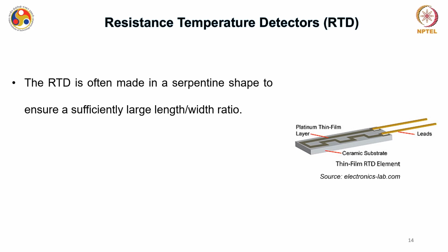Okay. So this kind of deposition can be done in various ways. You can use the concept of shadow mask. Shadow mask is a technique that is used across microelectronic laboratories, at least, to deposit this kind of complex structure using a certain hard mask.